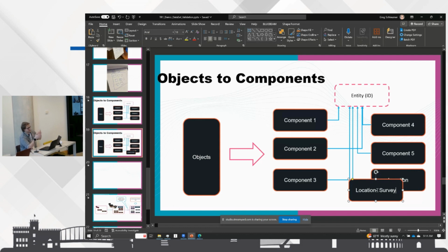Imagine the alignment starts on my left hand and goes to here, and every one of my control points along the alignment, I'm replacing with survey data. So everything forward to the right hasn't been built yet. It's been designed but not built.